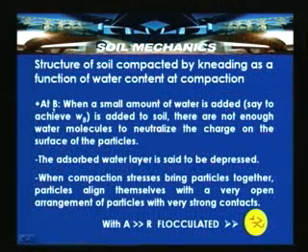So, at this point, point B, when a small amount of water is added, there are not enough water molecules to neutralize the charge on the surface of the particles. Still, some negative charges are prevalent, and with that there is some attraction taking place, and the adsorbed layer is said to be dispersed in nature.